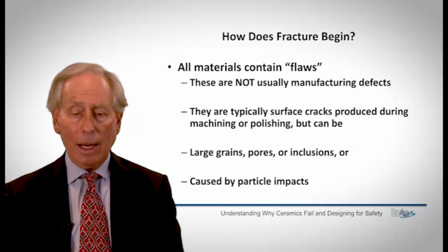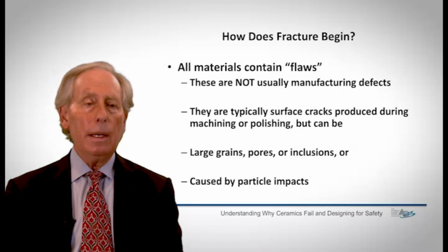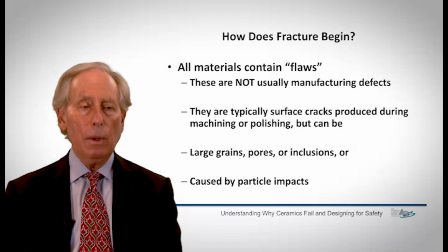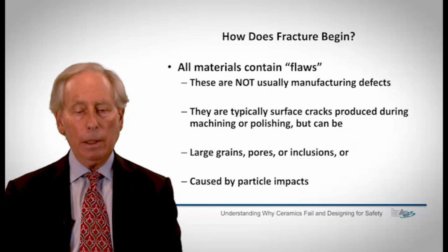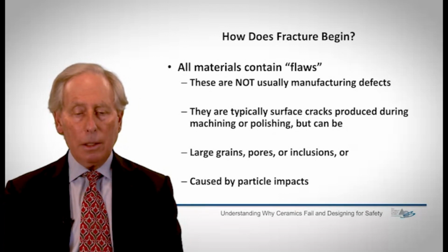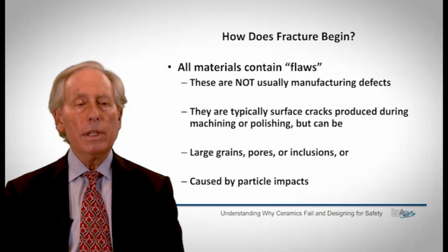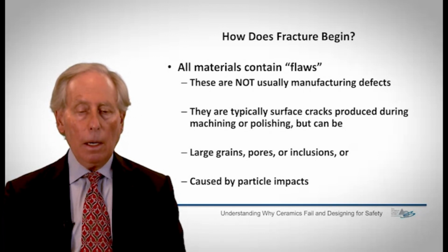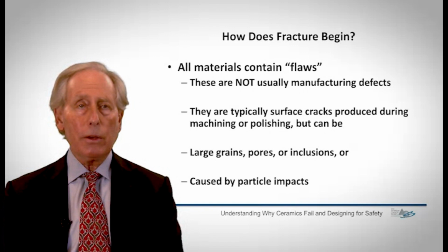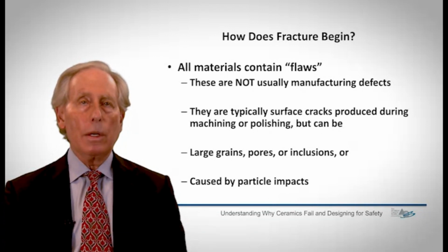So then, how does fracture begin? First of all, I want to point out that almost every specimen or component that you have contains flaws. And I think we want to get this out of the way fairly early. The flaws are not, we mean, manufacturing defects. We mean because the resistance to fracture of ceramics and glasses is so low that there are typically small surface cracks of the order of a few microns produced during machining or polishing that are the real source of failure.